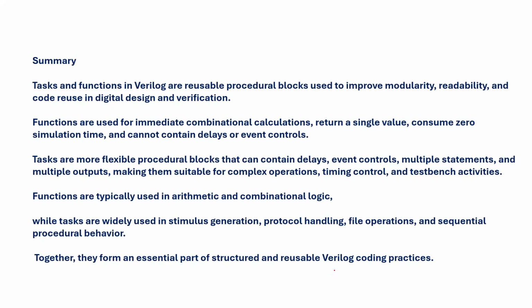Okay, so I told you functions and tasks in Verilog are reusable procedural blocks. We can use that. Suppose we can improve the modularity and readability and then code reuse while designing digital hardware, or for verification purpose.